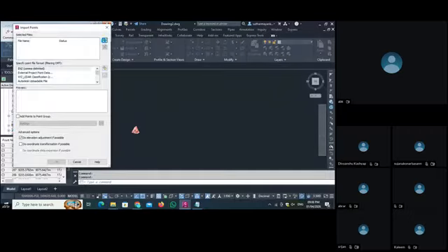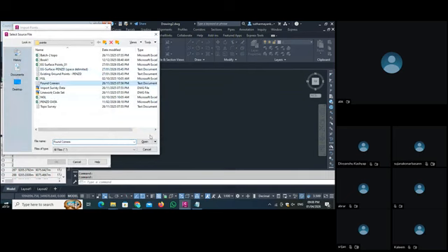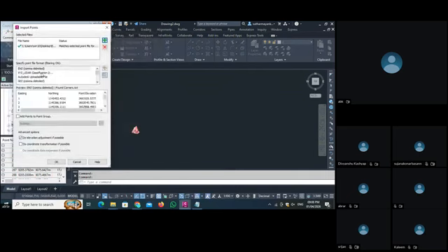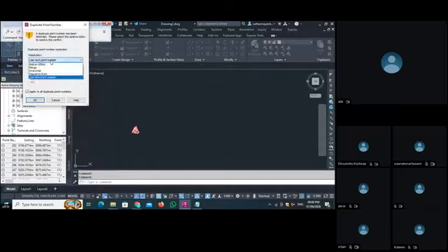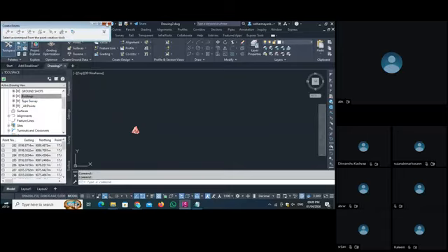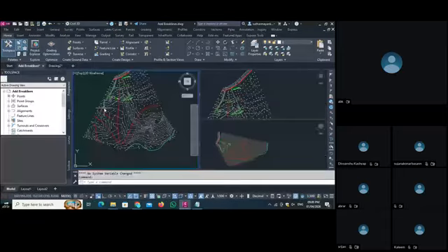So what we do, we try to import in a different format. If they provide us in this format, we can try it. We can add an offset like 1000. Let's take it. The next point number. See, previously we didn't delete that point, so no worry. I have another file, so we will try to import it here also.